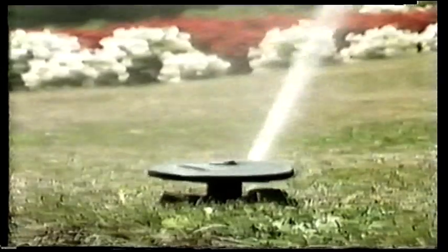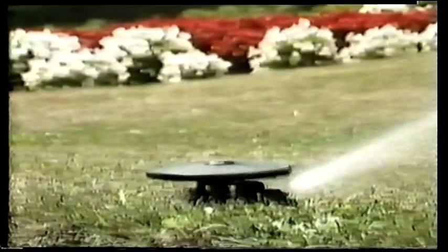During the interview, the survey team learned that an irrigation system is present at the hospital. The survey team should examine the type of irrigation system used. Does the system use chemical additives such as liquid fertilizers? In the absence of highly toxic chemical additives, protection can be afforded through the use of a pressure vacuum breaker. However, the utilization of toxic chemical additives would necessitate the installation of a reduced pressure principle backflow prevention assembly.